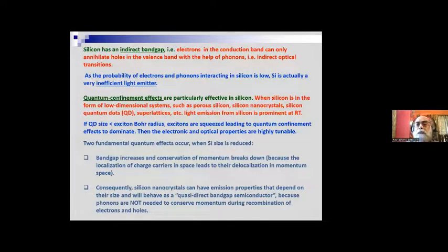Now we are actually going to the actual topic of my talk, where we are preparing a quantum well structure. Actually, that is a silicon germanium quantum structure. We are also making a quantum well like gallium arsenide, aluminum gallium arsenide, and also a superlattice structure. These are all quantum structures. A superlattice structure means there is a periodicity in two materials. We are growing silicon on germanium, then again silicon, again germanium, and this periodicity goes on for many layers. There could be 100 layers, there could be 200 layers.